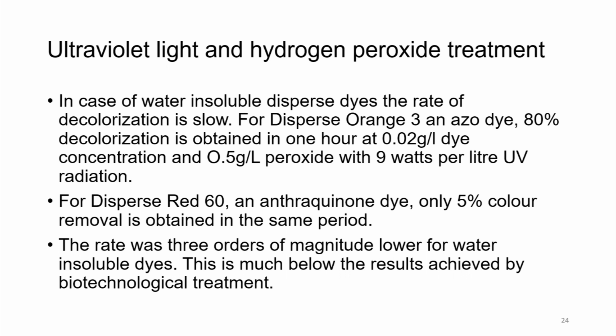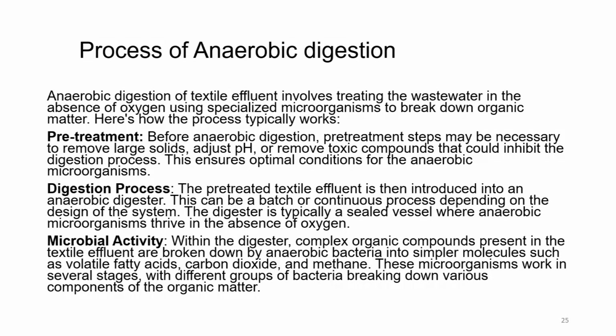The rate was 3 orders of magnitude lower for water insoluble dyes. This is much below the results achieved by biotechnological treatment. Hence, we can say that for insoluble dyes, ultraviolet light and hydrogen peroxide treatment methods are not the optimal method for carrying out the color removal.